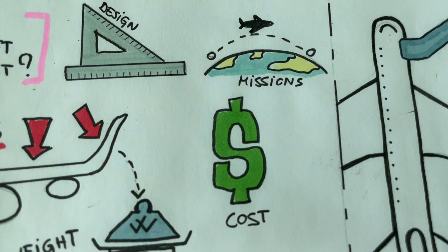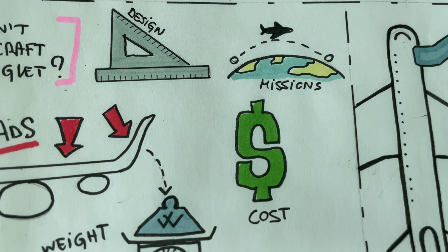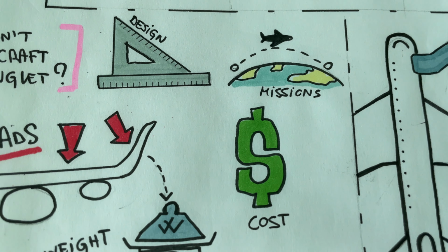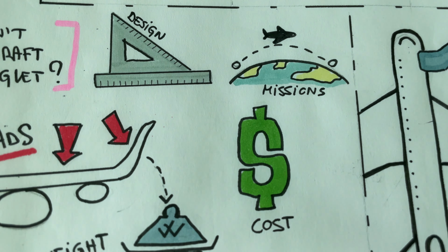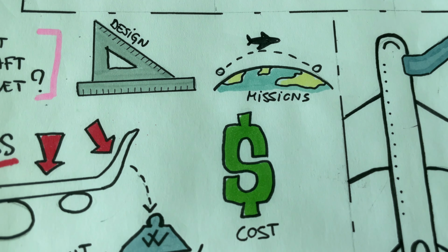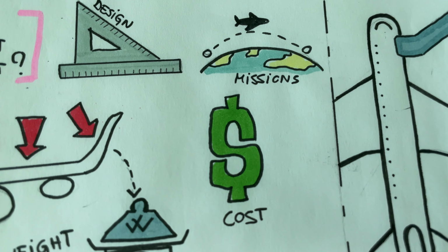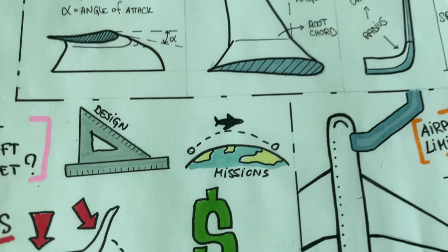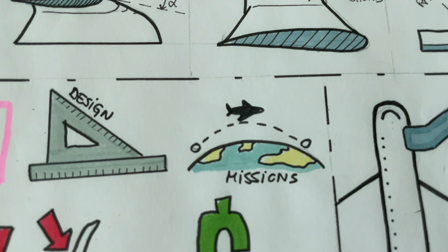Don't forget about this. Winglets increase the manufacturing and maintenance costs. For example, for shorter flights, the fuel saving may not justify the expenses. Then we have the kind of mission.